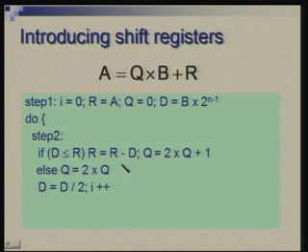Shift left and set the least significant bit to 0 or 1. Operationally this becomes easier. It is basically the same thing. First time we were placing b such that there was a shift of n minus 1 positions. So we ensure that d is initialized to this number, and subsequently move d right by 1 position every time.